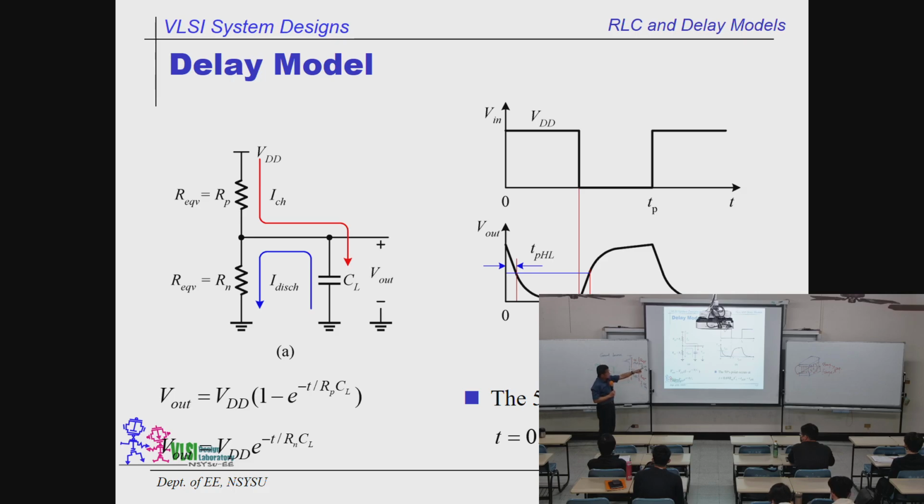So if you add the load over there, then certainly you are going to ignore all the parasitic capacitance over here. The only thing you have to worry about is the resistance. That is why I asked you to add the load, because that is the main pole. That is a major factor, the major problem of the delay. That's the C load because it's big.